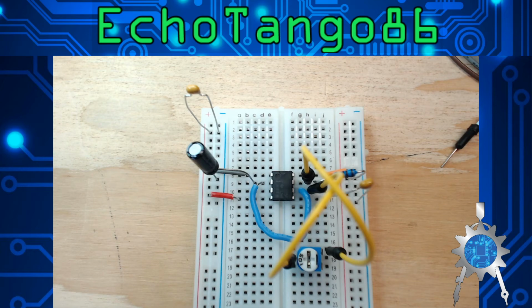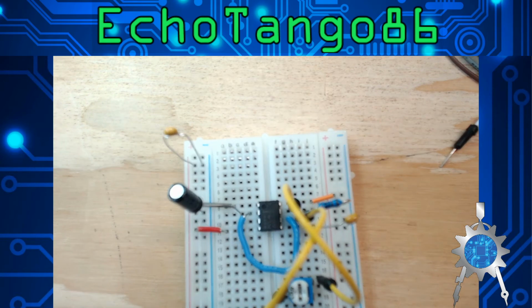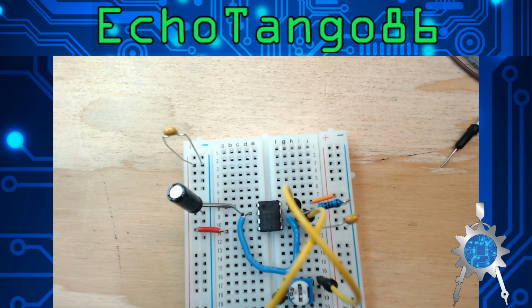What color should we do? Red, blue, green, blue? Thinking blue LED would be cool. We're going to grab a blue LED and a 200 ohm resistor. Now it doesn't have to be 200 ohm. It can be more than that, a little less than that. But basically what we're going to try to do is make it to where we don't have too much current flowing through the LED and the LED burning out.